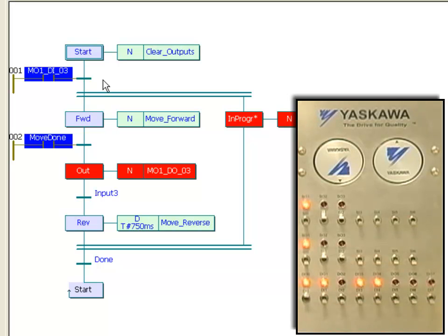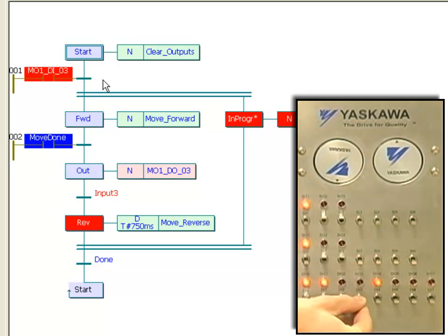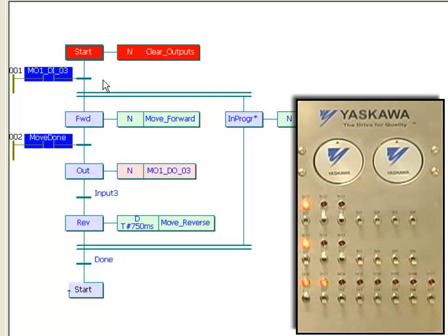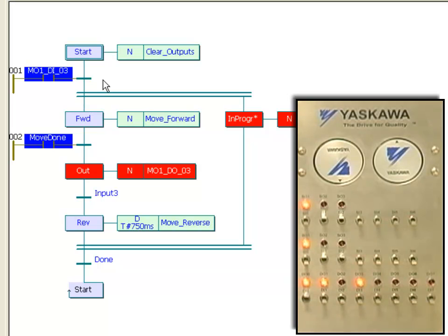And the sequential function chart shows very clearly that step. You can also see that DO3 is on. And running in parallel with that, the blinking action is taking place on DO4. If I turn on DI3 again, just momentarily, I don't know if you saw that there was a little delay. So let me just go through that again. Turn on DI3. And I'll turn on DI3 again.